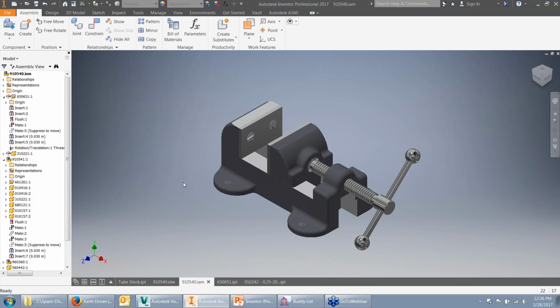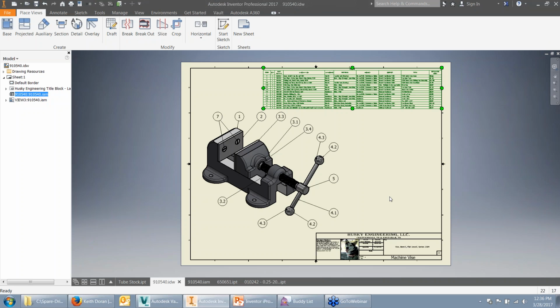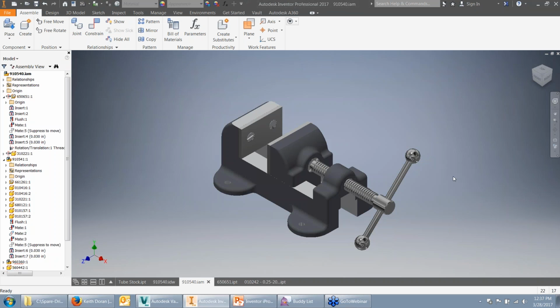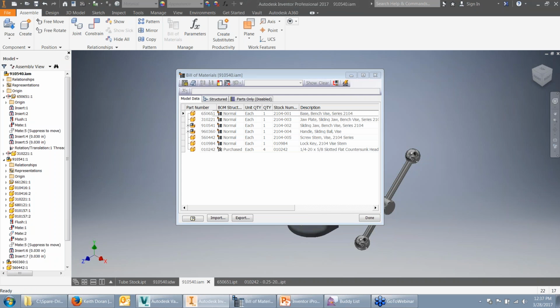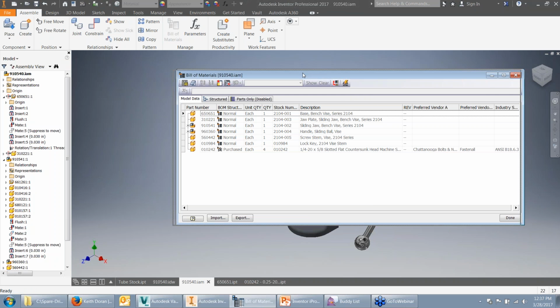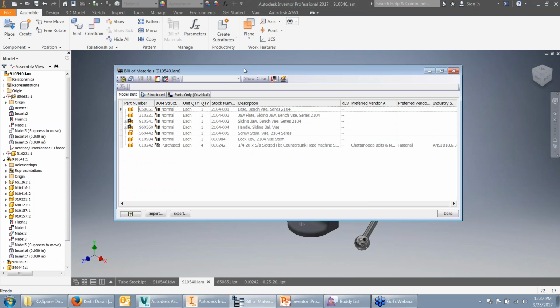So we're talking two different types of objects in Inventor, just because of how they've termed these objects. They're referring to this chart as a parts list. In the assembly environment, they're referring to a similar chart as a bill of material. There are some subtle differences in how they both behave and react.